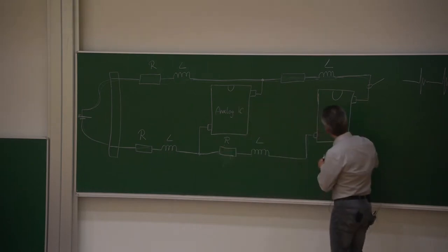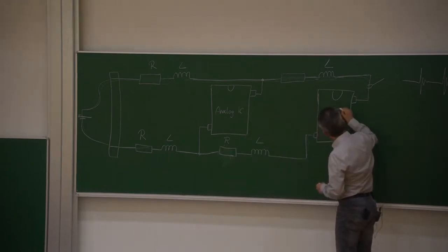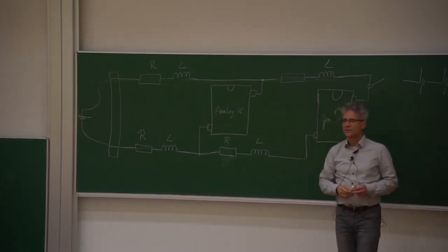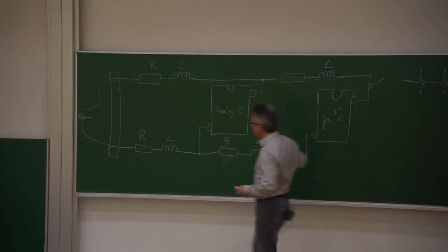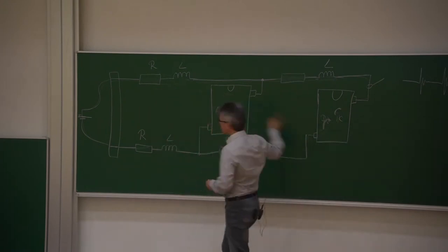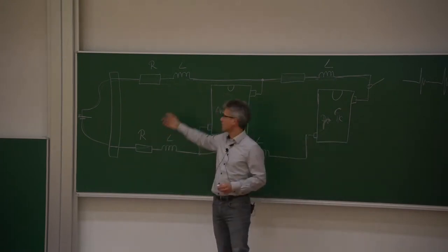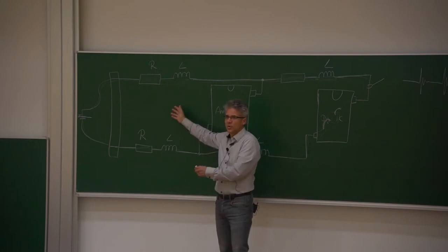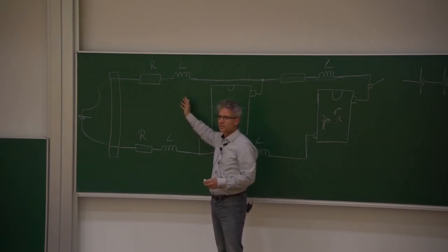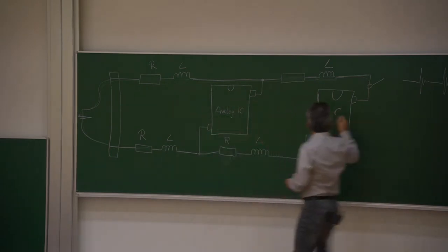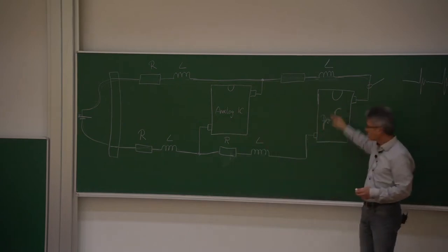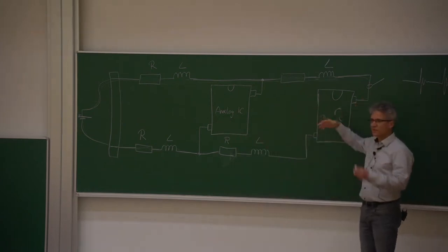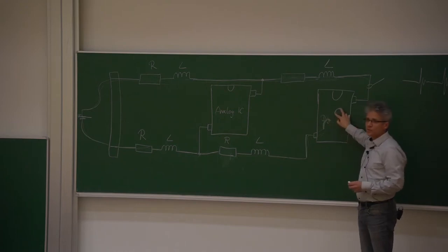And one small fraction of the big loop is related to the bond wire. Then we can somehow calculate the total inductance of the whole loop. This might be, I don't know, 1 microhenry, say. And then it's pretty clear that this small fraction of the total loop length, loop area, is also related to this small part of the bond wire.